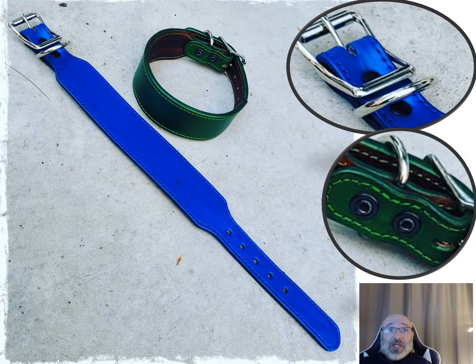So here's another application where I use these. These might be a little bit overkill in this situation, but these are dog collars that I utilize these for. And you can see right here, I'll turn on my laser, right there and right there, the top head, the round head of that tubular rivet. And I have different lengths of these for different applications depending on how thick my material is. And that's another calculation that you're going to need to take a look at to figure out how much rollover you're going to need over that there to hold it in spot.